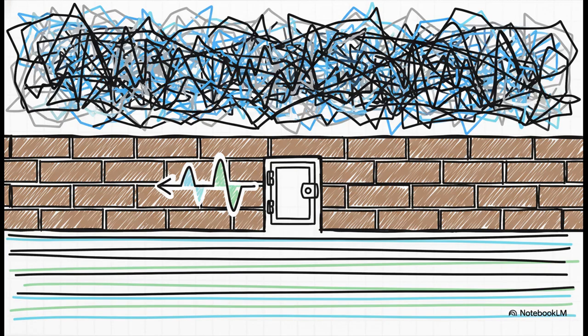By delaying the latching action to the falling edge of TCK, well after the rising edge has caused all the shifting chaos to totally settle, it guarantees that only clean, stable, intended test patterns ripple out into the active system logic. It's just a masterful piece of electronic isolation, and it proves exactly how robust and thoughtfully designed this 1990 IEEE standard remains for modern chip debugging.